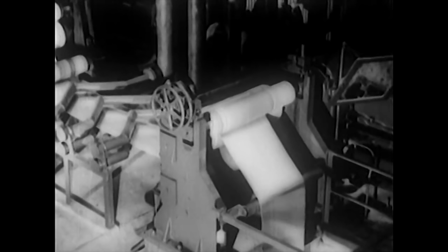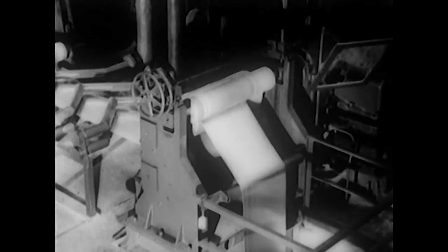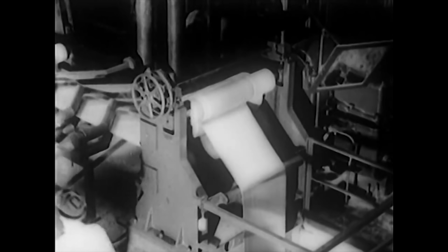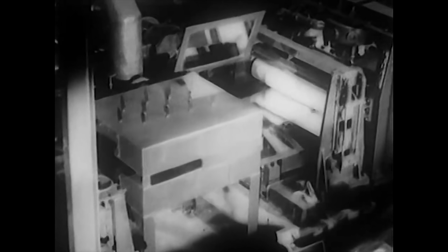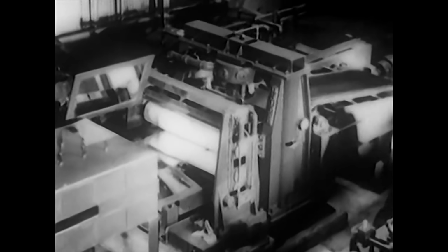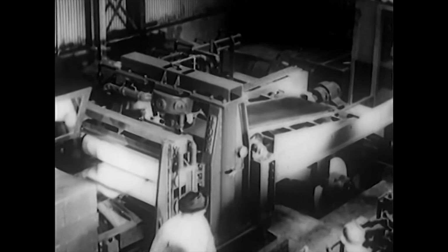After steel strip comes from its electrolytic tin plating bath, it first passes through a washer, then between hot air drying jets. At this point, the steel strip has a coating of tin that is relatively dull and porous. Next comes a vital step. The strip is raised to the top of the heater unit housing, inside of which is a series of high-frequency coils. As the strip comes down through these coils, induced electric current causes heat, which flows the tin almost instantaneously, greatly improving its structure as a protective covering.